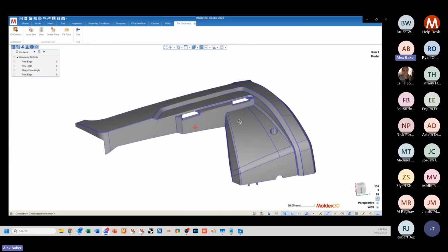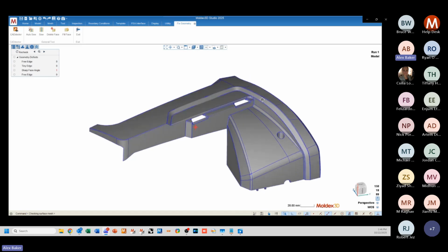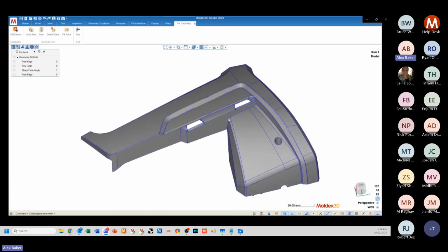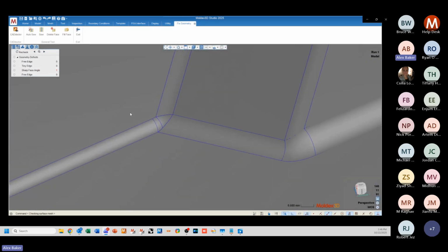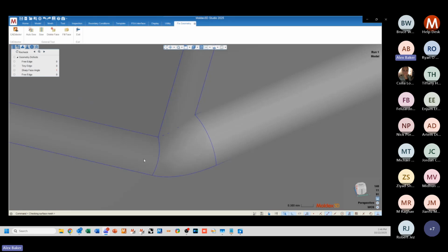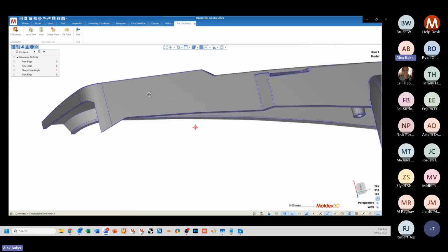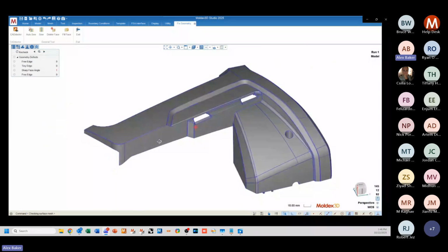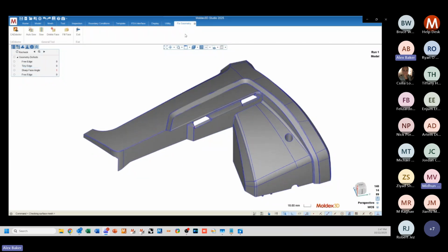And so CAD Doctor will never regenerate a surface for you automatically. So you can have a high level of confidence that the geometry coming out of CAD Doctor is exactly the same as the geometry that went into CAD Doctor, just with some surfacing connections shored up. So maybe if there was a slight mismatch between where a corner is in the surface connection, or maybe if there were some small features that aren't necessary for the analysis, maybe it will shore those up a little bit.